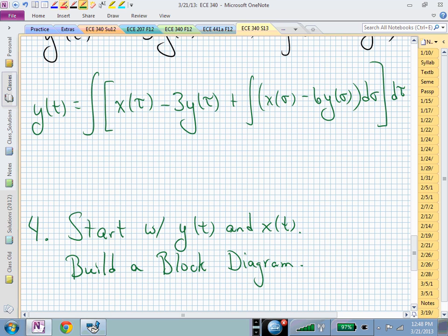And I don't know when to really inject this information. Do you remember what we had for our block diagram before where the state variables appeared? What did we use for the inputs to the integrals? Those were the derivatives, right? We had a q1 prime and we integrated it. The output of that integral was one of the states. The other integral had q sub 2 prime as its input. We integrate that, and the output of that integral is q sub 2, the other state.